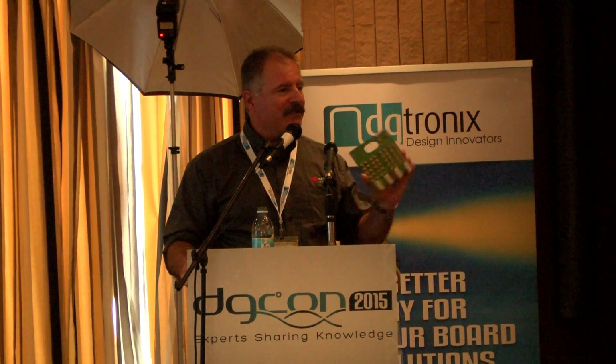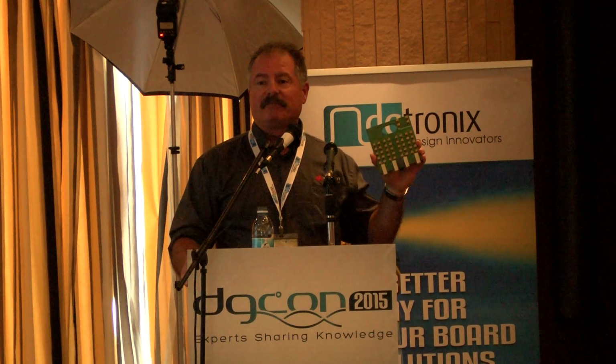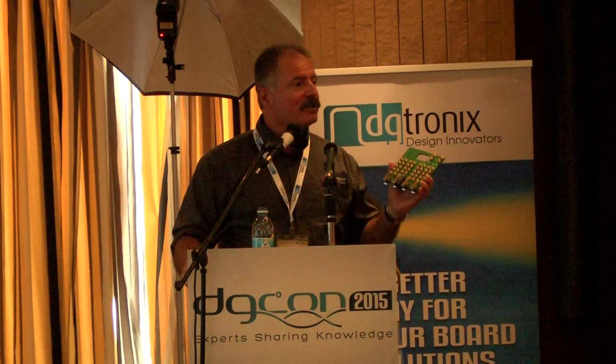If the open circuit radiates excessively, you'll see strange data that may become non-causal, which means if you try and put it into a simulation engine, it'll blow up. It'll make perhaps a passive device like a PCB look active or have gain, which is not possible. Strange things like that. So if that's the case with this methodology, the next step is use a short.